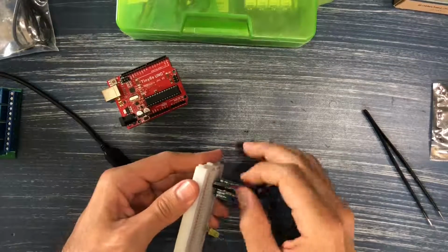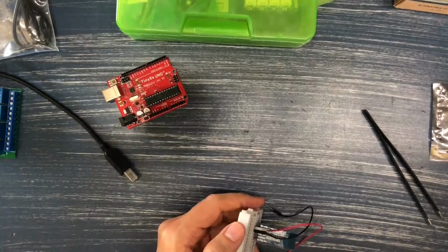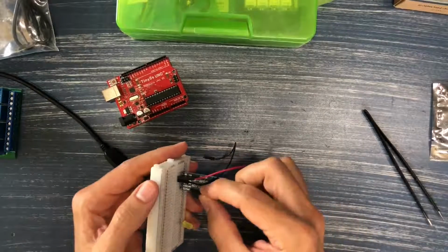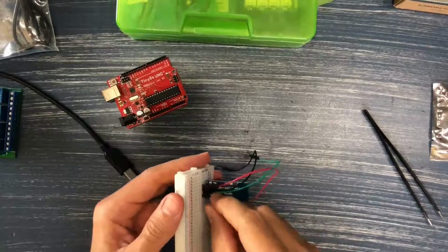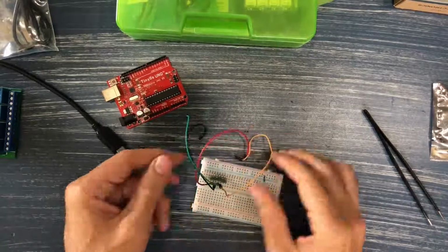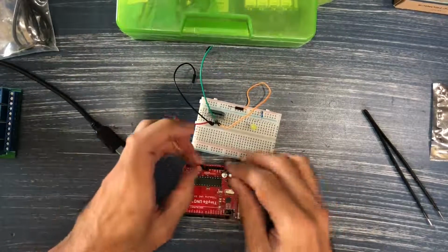This is important because it follows the same protocol. The VCC and the ground always go to the 5 volt in this case, and 0 volt ground. And the RX and the TX are the important ones here. And they connect to the Arduino